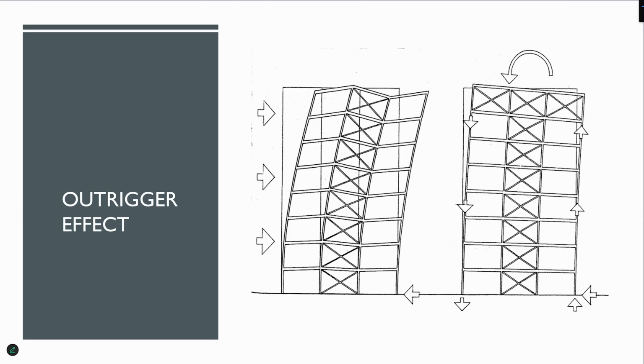The whole building becomes stabilized if you move it, and this is called a cap normally, or a hat truss, or a cap truss, at the top of the building. Many people use it. This is a shear wall internally, but both of them. So the shear wall is doing like this, and you add an outrigger to that to prevent this one from happening. You basically enforce this compatibility.